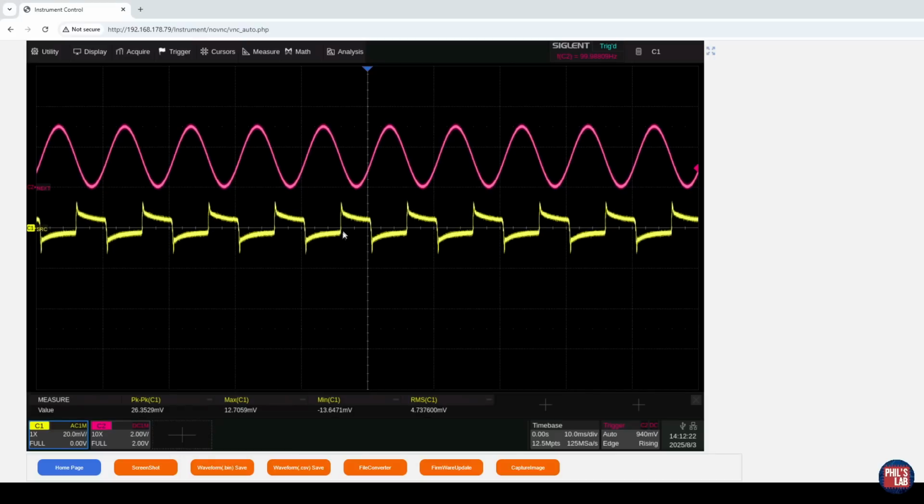And this is really cool because we can nicely see what happens when the current source engages. So when we go from the FET off at the lowest point of the sine wave to the FET fully on at the highest point of the sine wave. So on the rising transient, when we're applying a load current or we want to draw more load current, we can see our supply rail, the yellow trace below, actually dips down before it then settles, tries to go back to the nominal 1.8 volts.